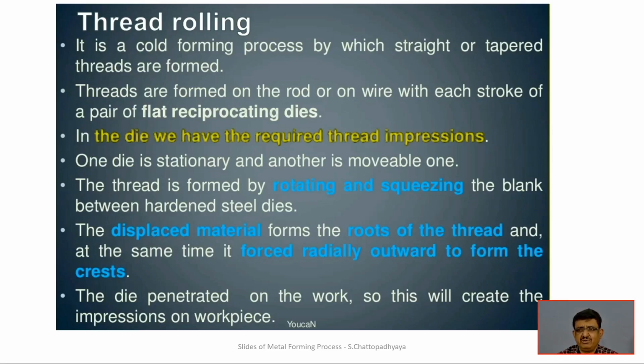Reciprocating dies, they will go for that, fix up, and according to that, with the hard impression, they will create all those things, rotating and squeezing between the hardened steel dies with typical shapes of the threads depending on their pitch. For each and every pitch, there is a separate dedicated set of dies, and according to that they put some pressure and squeeze, and the threads are produced in a higher quantity, and